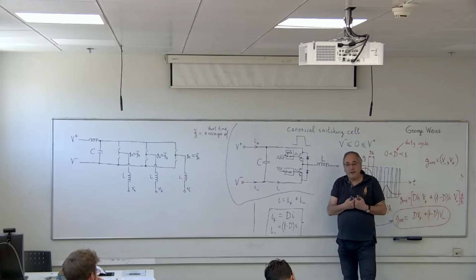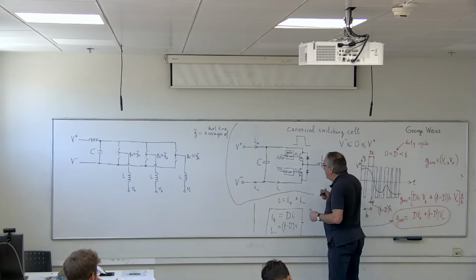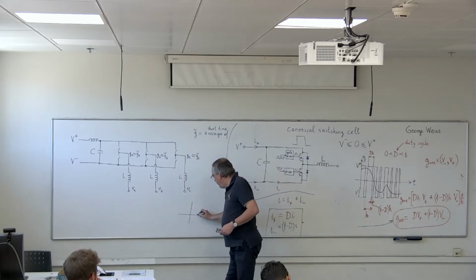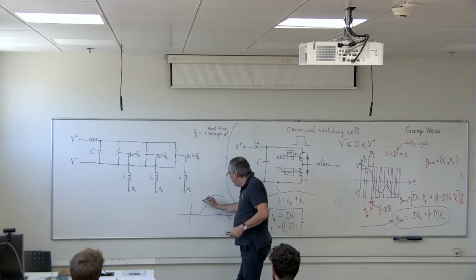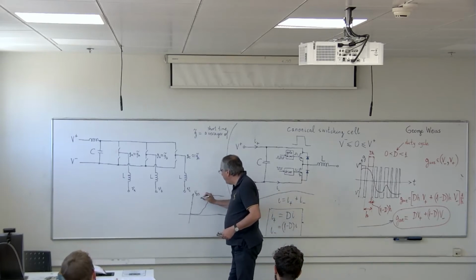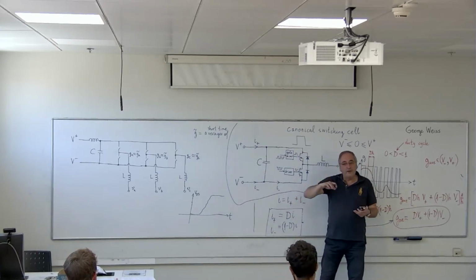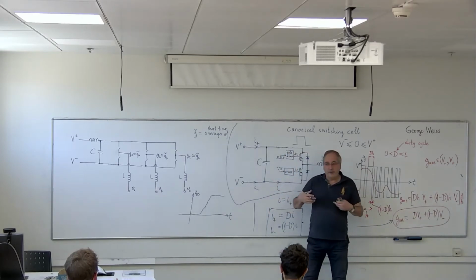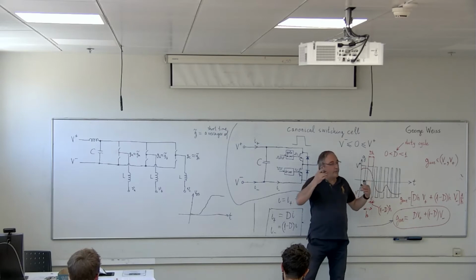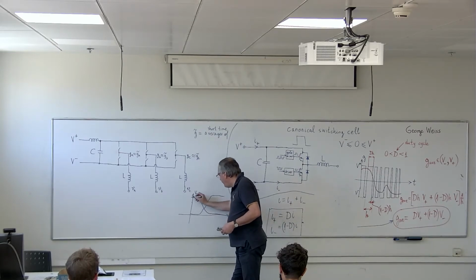That's when the switch gets hot. It gets heated during this switching, because if I show you the voltage on the switch, it goes up like this. If I zoom in on time, this is the voltage from drain to source. It goes up not suddenly, but if I zoom in sufficiently, I can see that this rise of voltage is gradual. And during this time, when the voltage goes up, obviously the current goes down, because what I'm showing here is a process of turning off the switch. So the voltage goes up when I turn off, and the current goes down. This is the current.